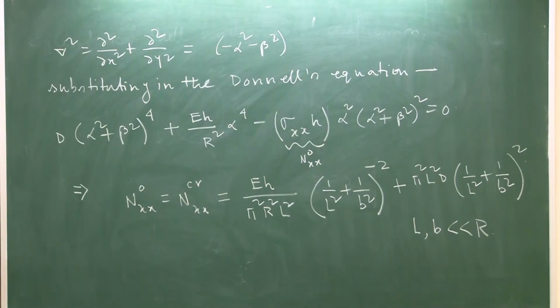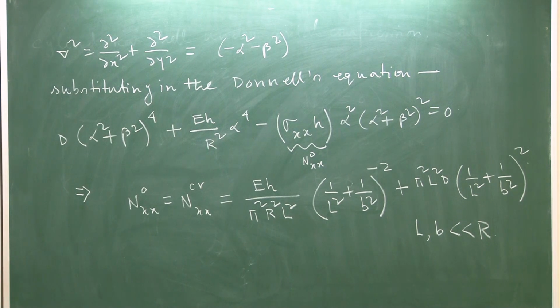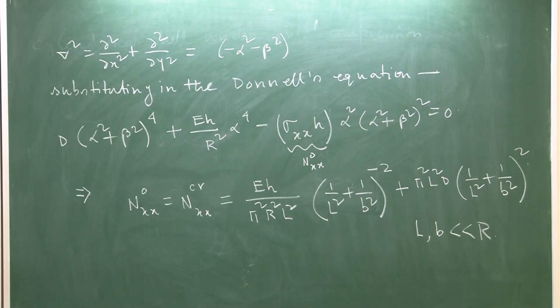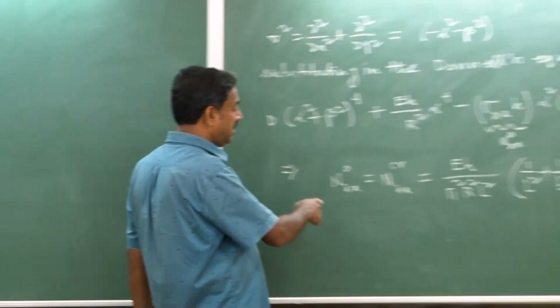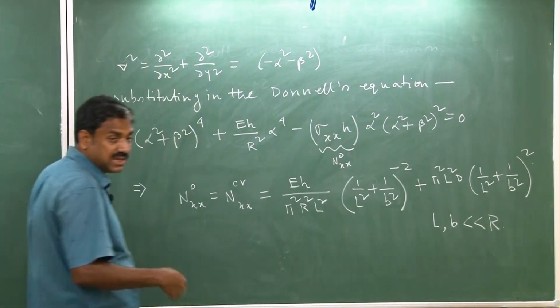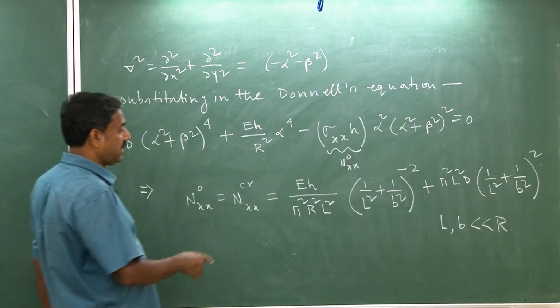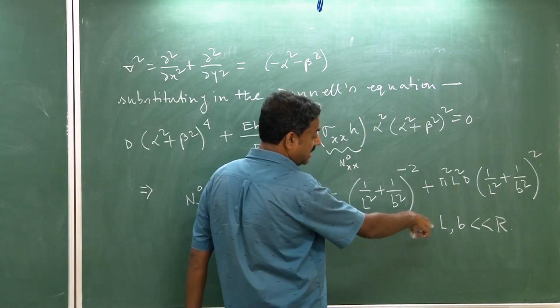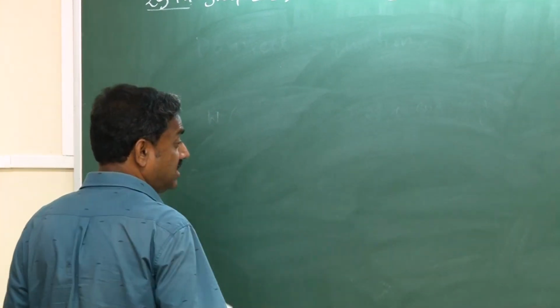Now, this minimization people have done, they made various assumptions. For example, the scientists who have contributed profoundly here are Alexander Chazes, whose book we read, and then Calladine and others, okay. The minimization we are not going to present here, but we understand that this needs to be minimized. Differentiate with respect to L and B; two input variables are there. So you set del pi del L and del pi del B equal to 0, and then you find it. This is an unconstrained minimization, but we will consider some special cases.